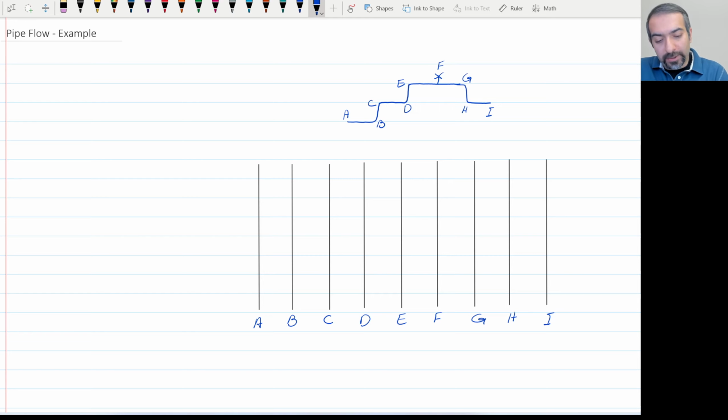Okay, so we assume that the pressure at the inlet, PA, is here. And let's first consider the case of inviscid. I'm going to use the light blue for inviscid. So what happens? As we go from A to B, the y-axis here is the pressure, and the x-axis is along the pipe. It's not really the horizontal distance, it's just along the pipe. It's like S, if you remember, for the curvilinear coordinate.